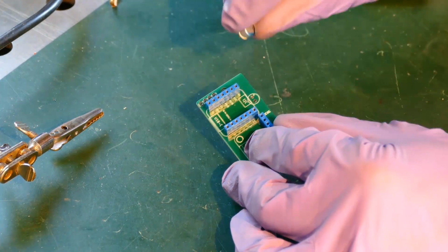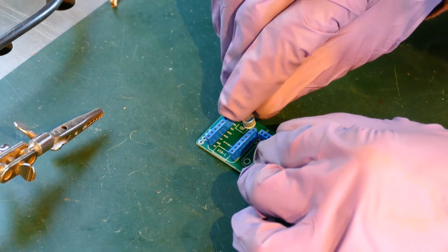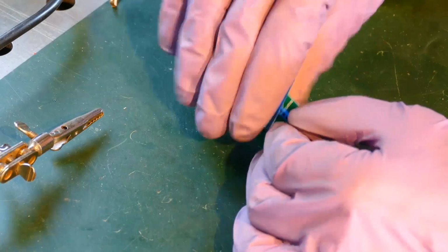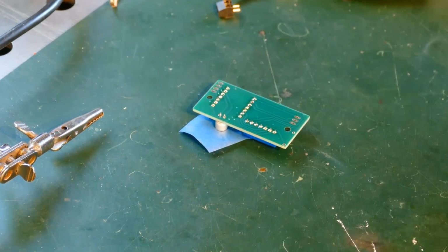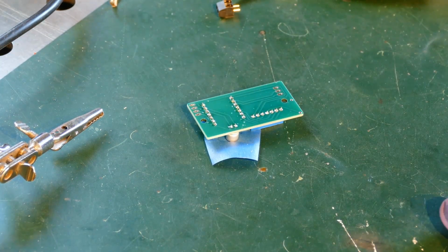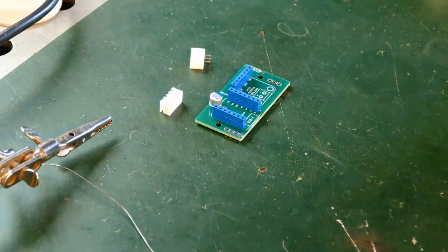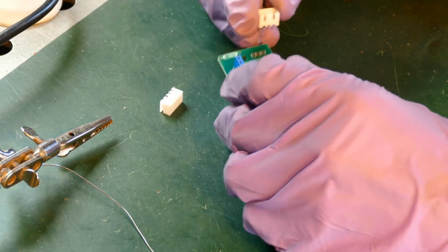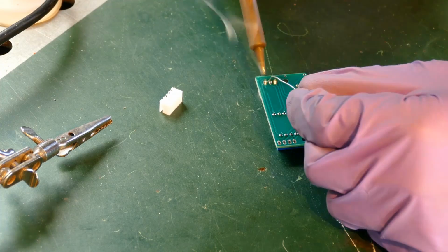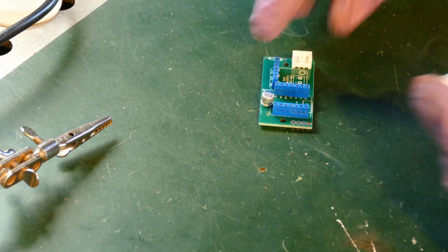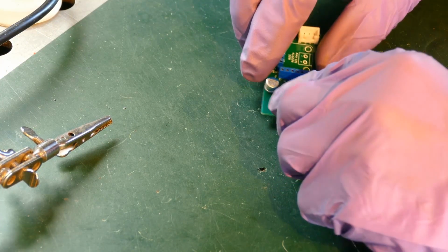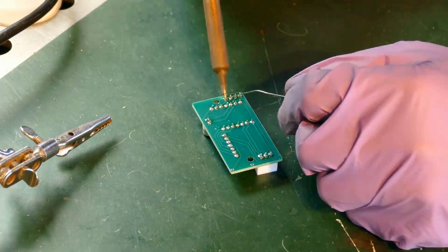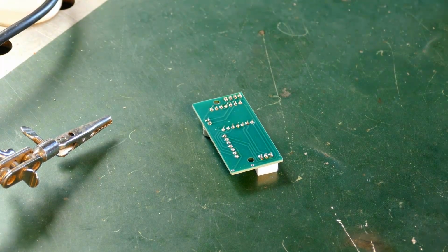Next, the 100 mic capacitor is added. It's temporarily held in place with some masking tape. I'm careful to align the negative end appropriately. It slightly overlaps the QT Py, but it doesn't matter because it actually fits underneath. The OLED display is connected with 3-pin and 4-pin JST-XH connectors. I went with 2 connectors because I didn't have any 7-pin versions. The male sides can only fit in one way, so there's no way to plug them in wrong.